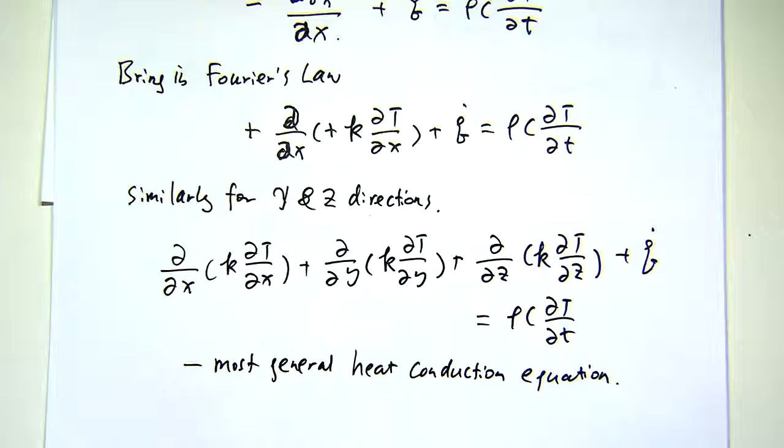I have some more questions. Yep. So while I was working on the assignment, in the saturated water table, there is enthalpy for fluid and gas, and h_fg, which is the enthalpy of evaporation. Where do I use it? h_fg is basically the difference between the two. Yeah, you don't use it, because in your calculation you're dealing with either the saturated liquid or the saturated vapor. Yeah, because for the other refrigerants such as propane, they don't have the h_fg, and only the water one has one, so I was curious. Yeah. Thank you.